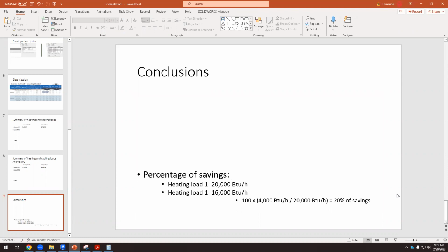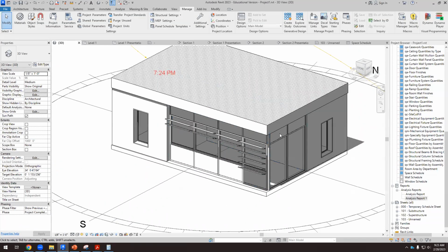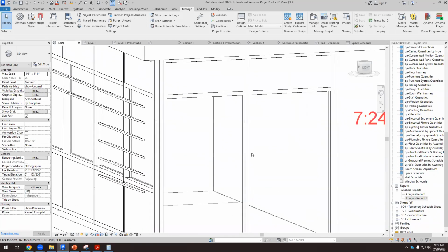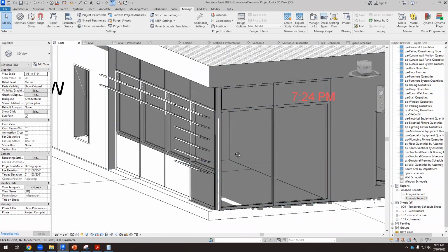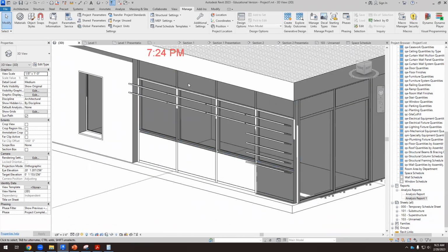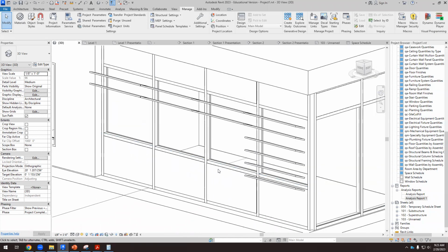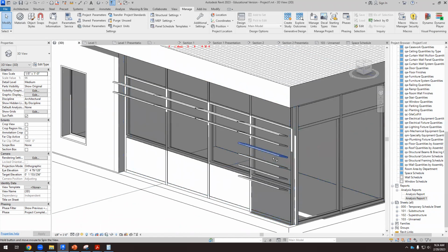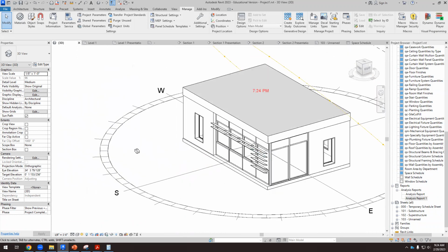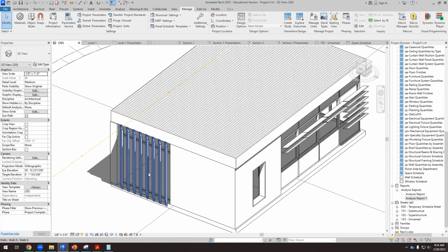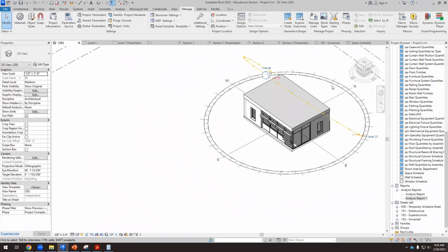So within the conclusions, you want comparisons. Yeah, so the first option will be a curtain wall like this one. In this curtain wall, we didn't do anything, it's just glass. And then the second option, you have to do a curtain wall like that one, reducing the glass area, but without reducing the curtain wall area, and using some shading devices. And there will be different strategies for the south and the east and west curtain walls. Okay. And then it should work.